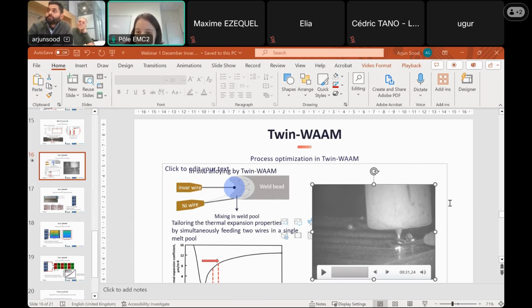And there is an additional question from Elia. Is there a negative effect on the microstructural properties due to this chemical gradient, unlike thermal expansion? In terms of microstructure, no, because if you saw earlier, between iron and nickel, there is a single phase austenite region present. So if I move on further from 36 to 8% of nickel, then you will still have a single phase microstructure that will be available to you. However, like I mentioned, if your parameters are not controlled properly and you result in some kind of segregation, then you could end up in a dual phase INVAR, which is unwanted as it impacts your thermal expansion properties. But between iron and nickel, there is complete solid solution solubility, and by mixing them, you do not have any negative influences on the microstructure properties.